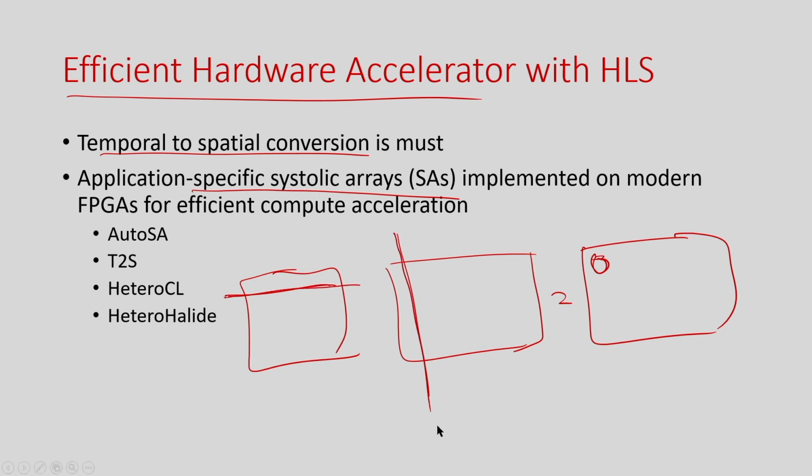So, what I can do is break this into small components, and just do this part of the computation one time, next time I will do this component with this one, then next time I am going to compute this with this one, right. I can split my whole array into these small components, and basically a multiply and accumulate operation is happening. I can do this and this one time, and then do this in parallel, and so on.